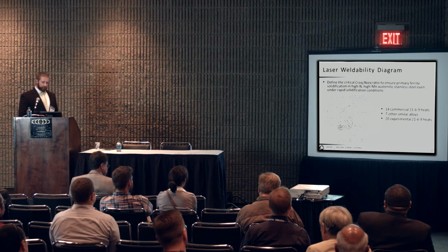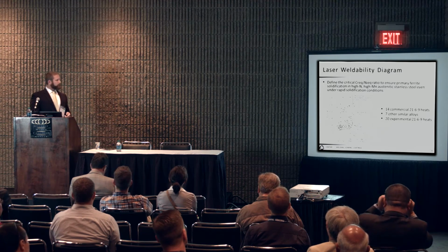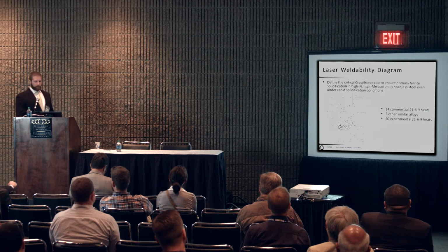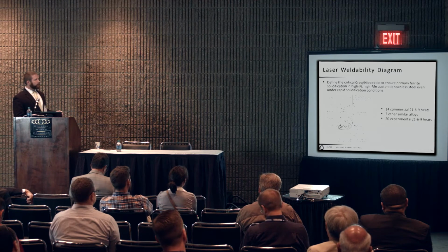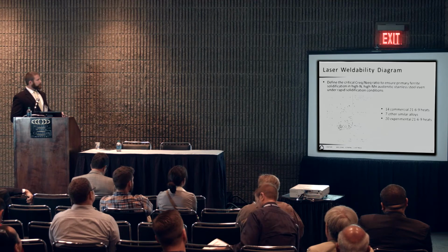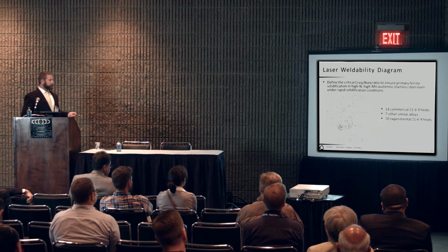Then going to the second set of results, trying to develop a laser weldability diagram and tie alloy composition and impurity content to cracking for the 2169 alloys. We did this with basically 3 different subsets: 14 commercial heats of 2169, 7 other commercial heats of similar alloys, so similar Nitronic alloys, as well as some other specialty high nitrogen, high manganese alloys, just to see where they fit in, and then 20 experimental heats of 2169. And that 20 includes the alloys looked at in the sulfur and phosphorus variation.